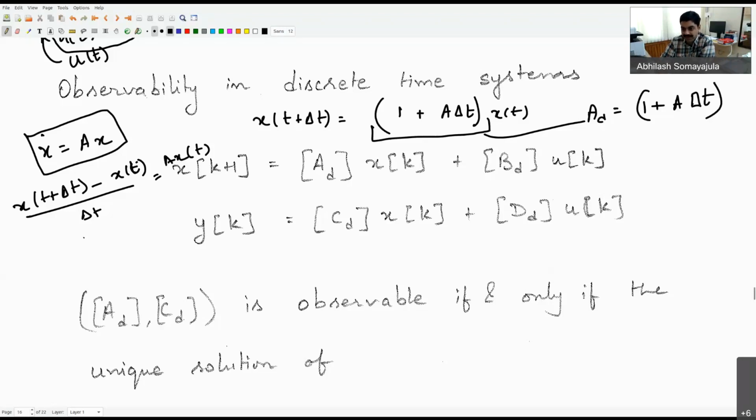You generally tend to apply them in discrete time because your measurements are coming at discrete times. They're not continuous. They're not analog signals. They're digital signals, which means you're getting those values at some discrete time. That is why you have a sampling rate for your sensors. When you say that my IMU is measuring samples at 200 Hertz, it's coming 200 times per second. Discrete values are coming at that rate.